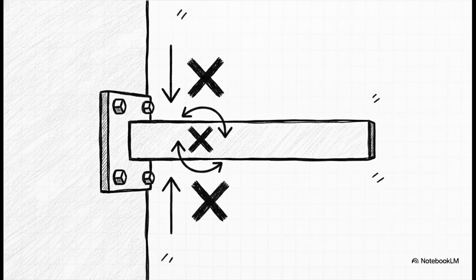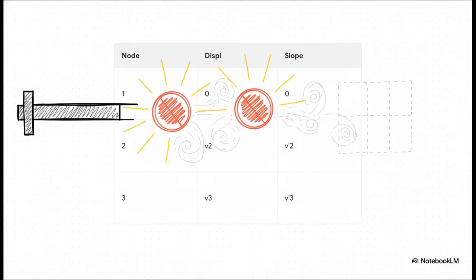Displacement at point 1 is 0, so V1 equals 0. The slope at point 1 is 0, meaning V'1 equals 0. And logically, if it literally can't move, it definitely can't accelerate. So our acceleration variables at point 1 are identically 0 too. Now, by simply plugging in those zeros for V1 and V'1, we brilliantly eliminate whole sections of our matrix. Remember, anything multiplied by 0 just becomes 0. So the first two columns and rows of our generic matrix essentially just vanish from our active problem solving. By just observing the physical limits of the beam, we have cleared out a massive amount of mathematical noise.